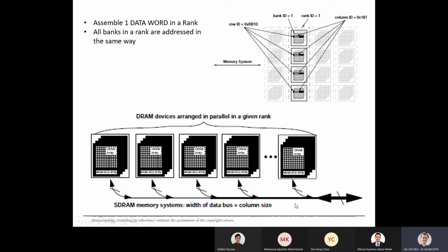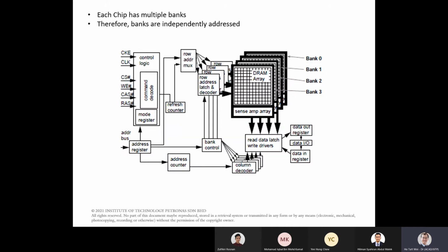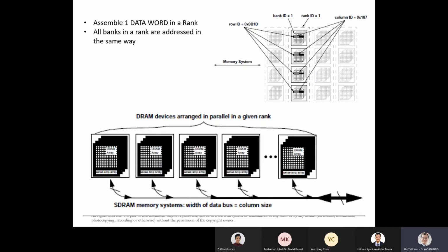So this is about 32-bit, 64-bit, 128-bit. And why don't you have a 32-bit wide chip? Because with 32-bit width, there are too many DRAM arrays in parallel. When that happens, again, capacitance slows things down. So there's a kind of sweet spot. Up to about 16 bits is enough already, right? It all goes back to speed.